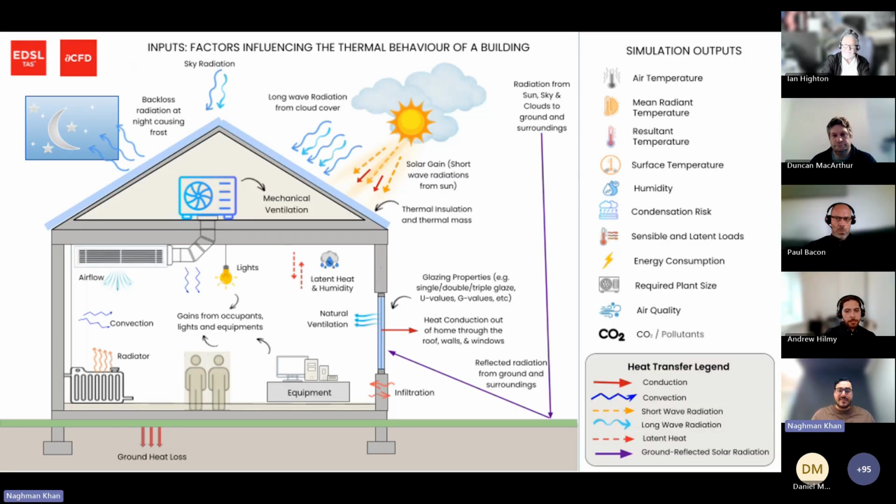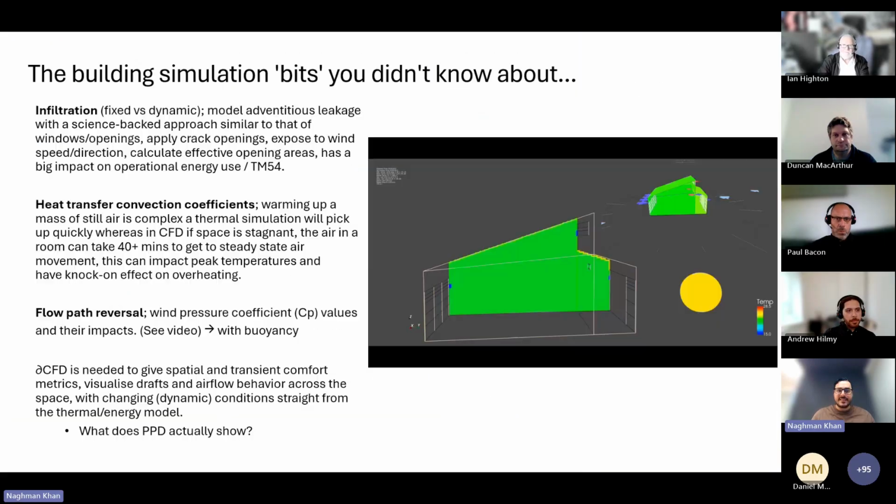So Ian, moving on, here are things or bits you might not know, which is the really interesting bit and the purpose of this webinar. The first two, to a degree, have come from two different projects. We did a lot of analysis of One New Change, which is a Land Securities building in central London near St Paul's, and learnt an awful lot during that process. The three things were infiltration leakage, thermal leakage, and huge quantities of simultaneous heating and cooling.